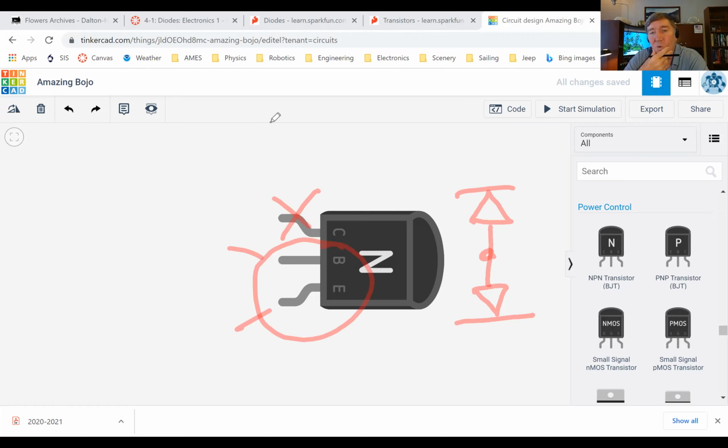I wonder what the threshold voltage, also called the forward voltage, of that diode would be. In your homework last night, you remember we had two different types of diodes, the LED and the regular diode, and the threshold voltages were very different for them. First thing I want you to do, right now while we're all together, is let's measure the threshold voltage of the lower diode.